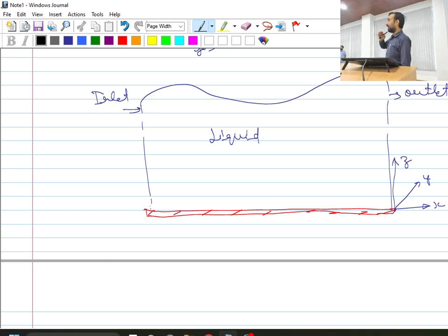Whenever a solution is marching in time, we have to tell at t equal to 0 what our physical situation is. So the values of all the field parameters, like velocity vector and pressure, because right now I am only talking about fluid mechanics.